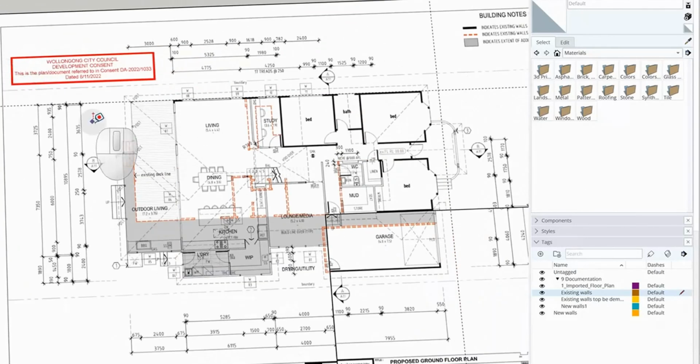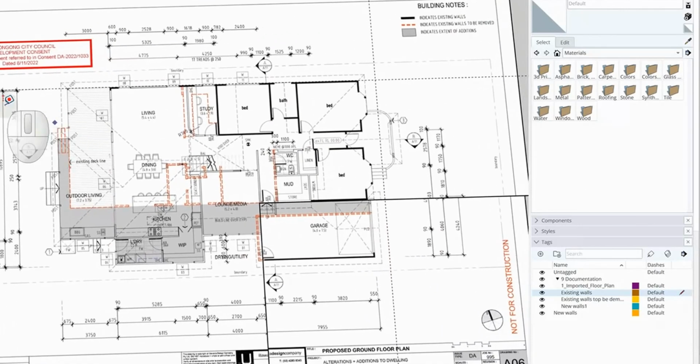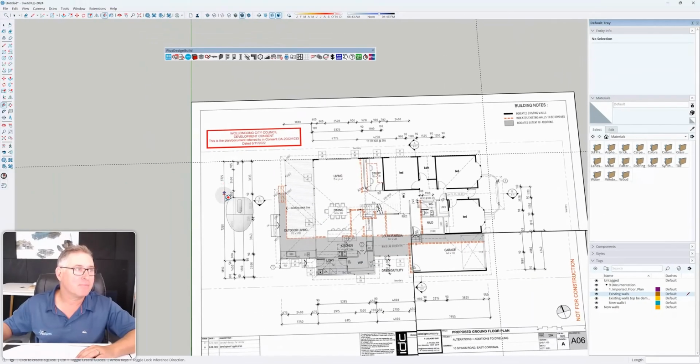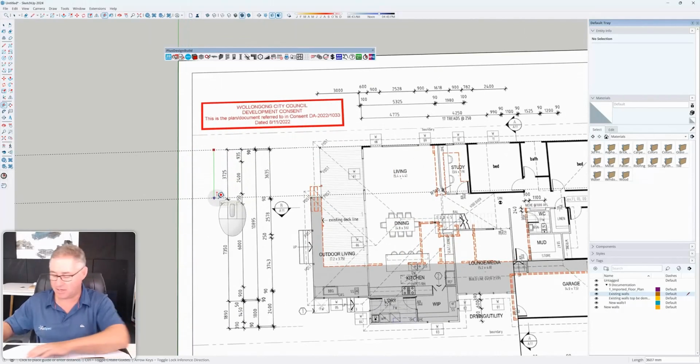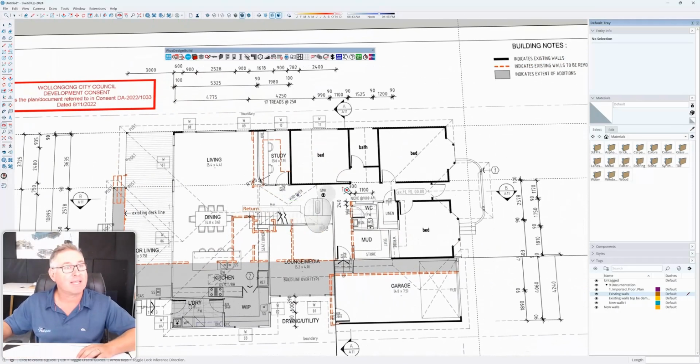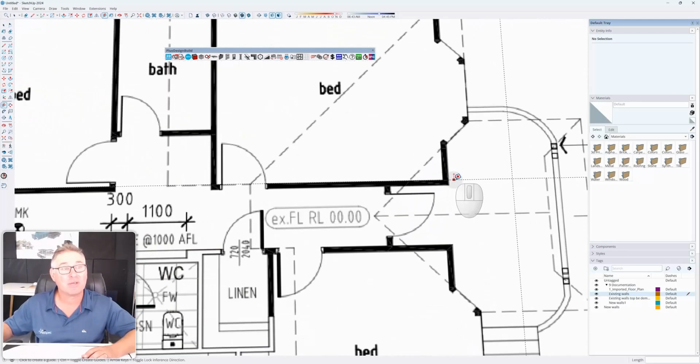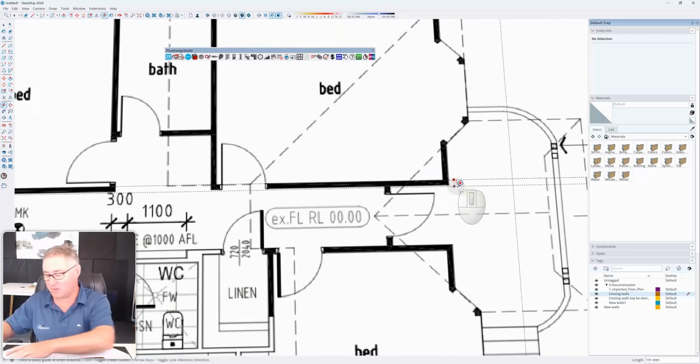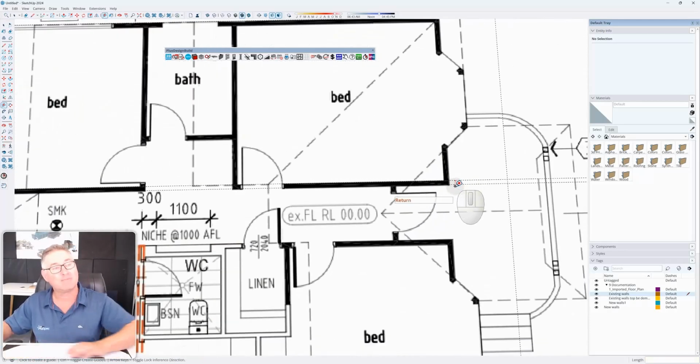Now, depending on the draftsman or designer that did this, usually these strings would actually line up with all external walls. So if I just went to here and typed in 3725, enter, it's actually not lining up. So this guy hasn't done that. Oh, it is an external wall here, sorry. And then I'm going to type in 90 mil for my other side of the wall, enter.